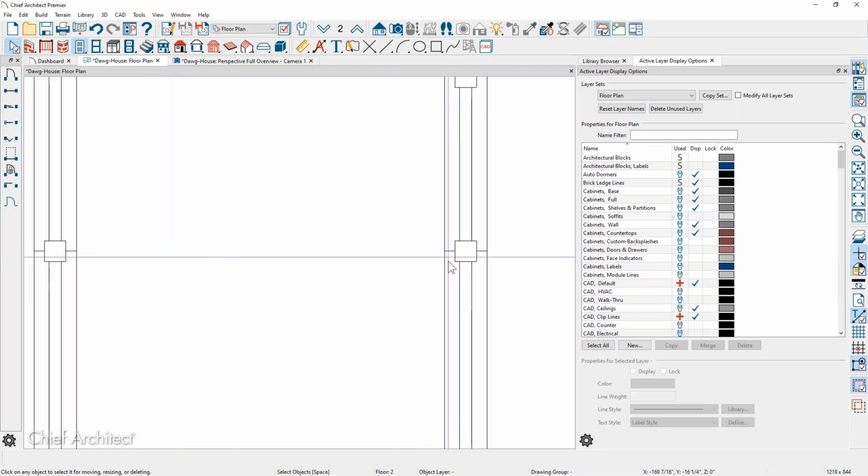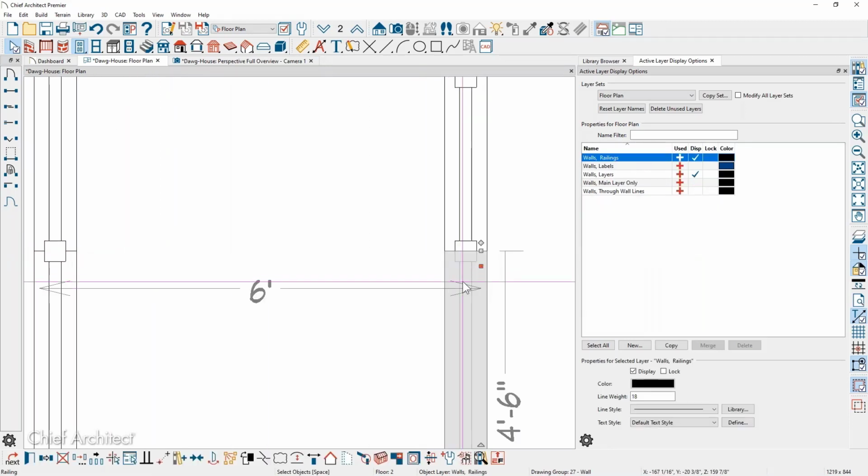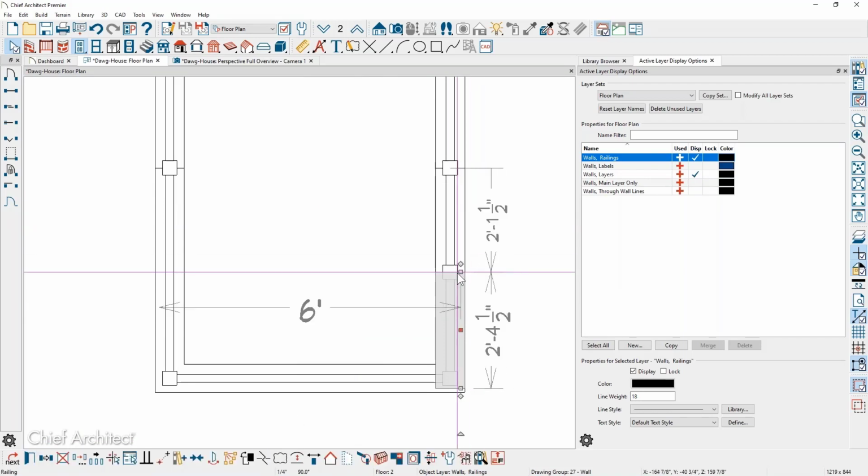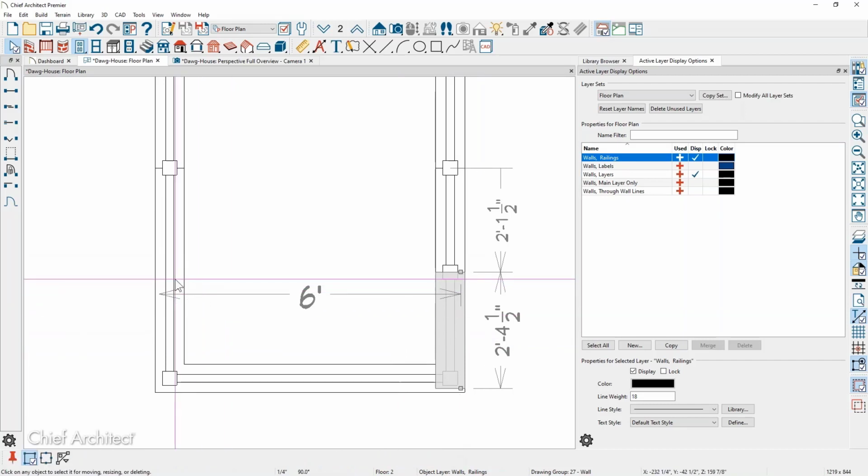You see a little line in here? That's a break, wherever you put a break. So if I go ahead and use the break tool, which is in the bottom edit menu, and let's just put a break down here. See, it creates another post, and then put another break over on this side. Use the crosshairs to line that up.